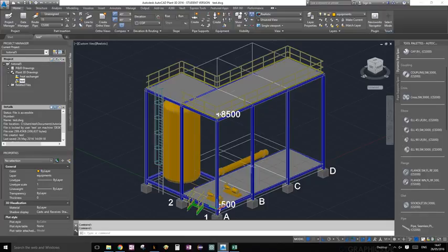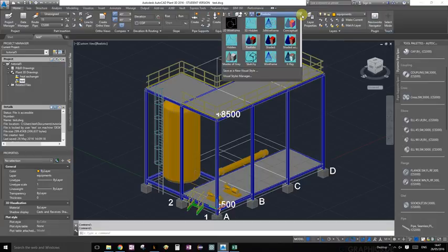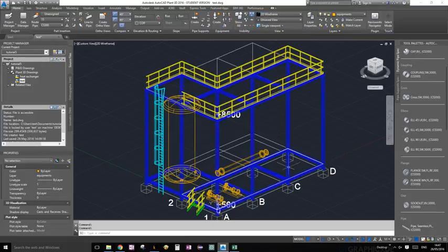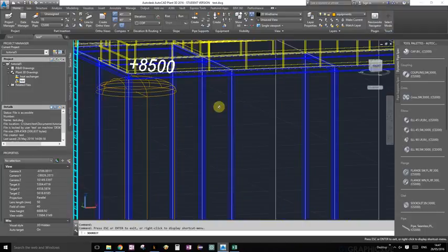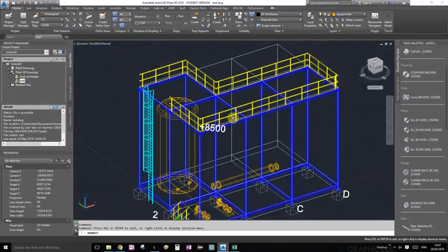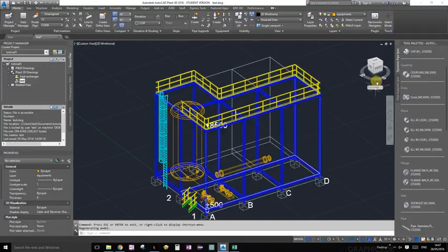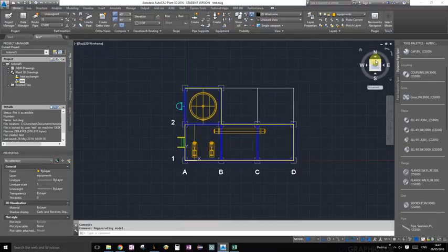Right now we see a 3D representation of all of our objects. So under the Home ribbon and under the View palette, the very top drop down box, right now it should say Realistic or something else, but we're going to choose the 2D Wireframe. As you can see, once I selected it, it turns it into 2D wireframe. It's still 3D, but it shows you the frame and nothing more, which is helpful here. And we're going to choose our top view. Go ahead and choose top view.